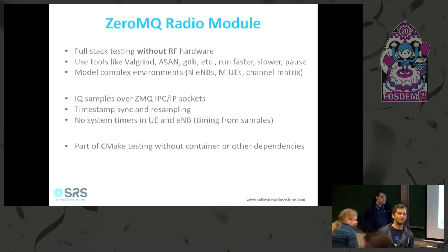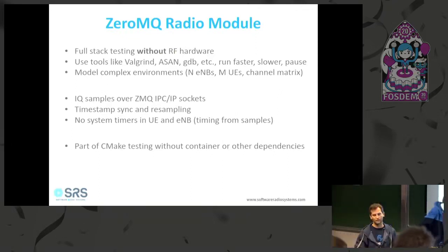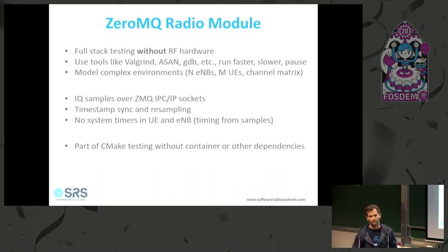Very good. We're really looking forward to that. So then the extension of that would be, yes, you could perhaps run the eNB on the Pluto itself, definitely on the host, but you still have your USB 2 bandwidth limitation. So you can definitely run the eNB, and probably a small LTE cell, 6 PRBs, 15 PRBs, but definitely not the bigger ones, because they're like 20 megahertz. You're not getting that over the USB 2.